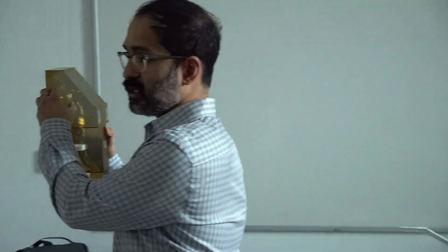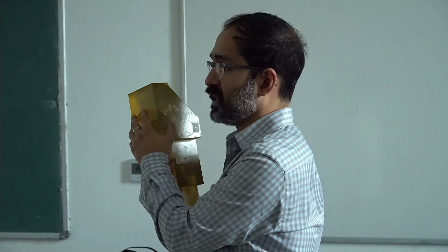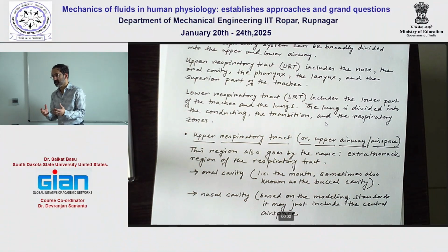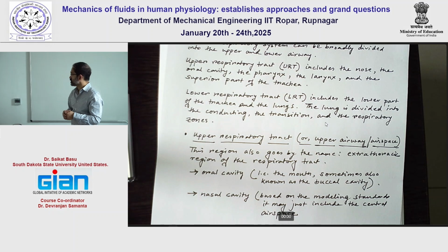So this sac-like structure that is jutting out, or this region under the forehead, those are all sinus cavities. Now there are 4 different kinds of cavities, and we are going to look at them in a moment. But these cavities, they don't take in much air flux. So most of the air that we are breathing in, it just moves through the median central part of the airspace, goes into the trachea and into the lungs. Not much goes into the sinus cavities that are adjoining to that central airspace. So for the sake of quicker simulation, most of the times we might take those sinus cavities out of the model and then model the airflow.